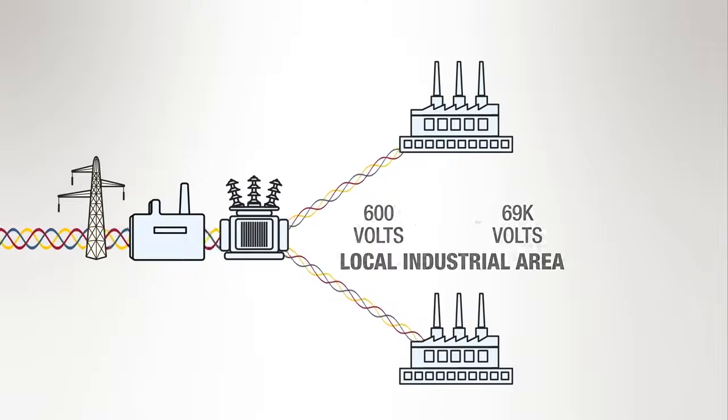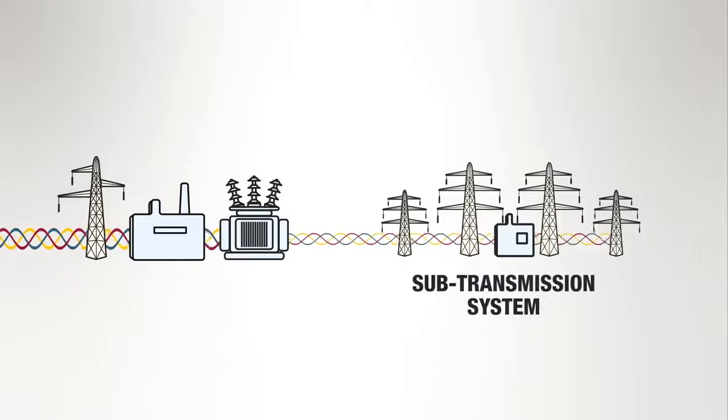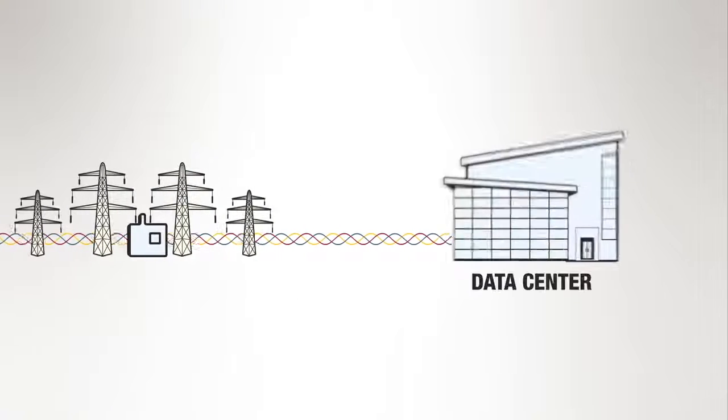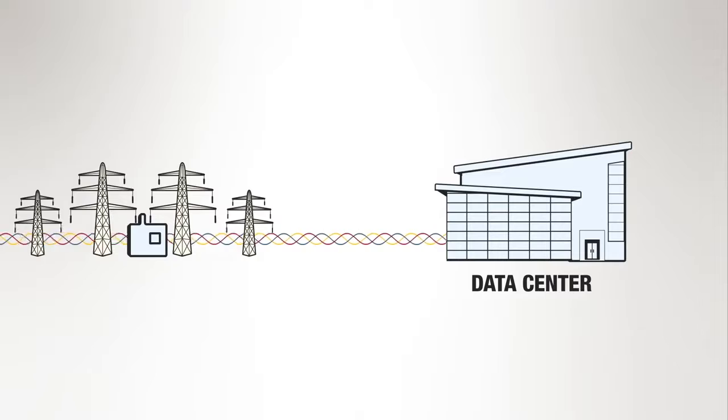After the voltage has been decreased, the power enters the sub-transmission systems for medium voltage customers. These customers have transformers, circuit switching, and protection to handle these voltages. They customize the power to the levels they need for their industrial equipment. They will take voltages that come in as high as 69 kV and use this power to run their 120 volt office equipment. Data center customers may take medium voltage, but they are more likely to have the utility transform the voltage down again for their use.